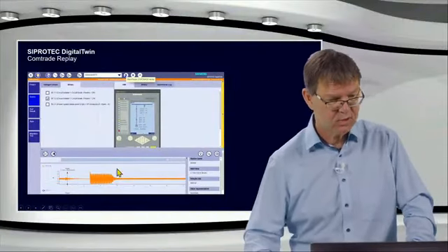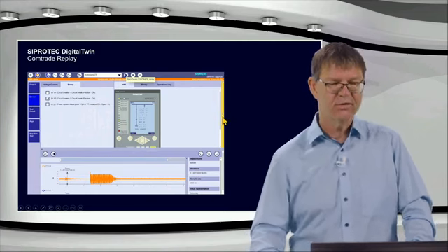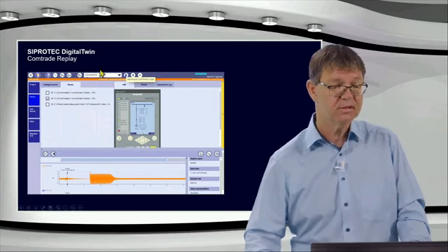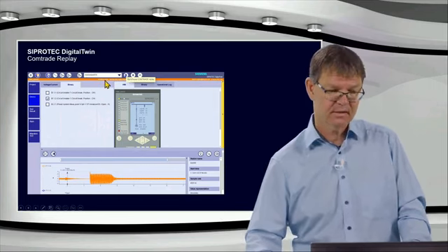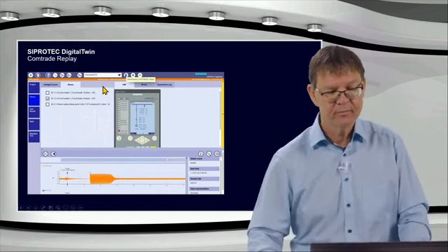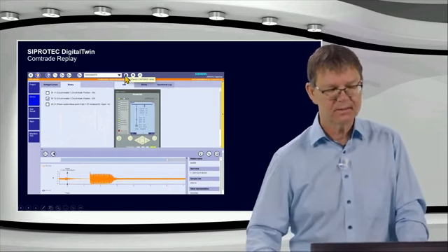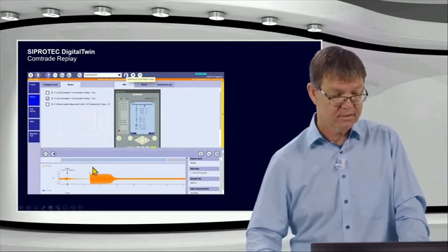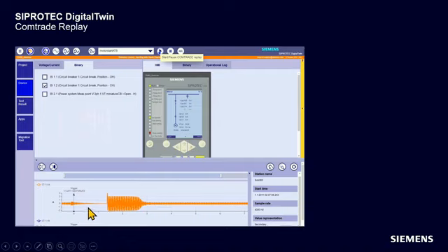Just one more thing which I would like to mention. You can also replay fault record. So if I have a fault record in a COMTRADE format like this here one, then I click here, I select this before and make some configuration. Then I click here on this button, start button, and then I replay this fault record. Here I can visualize the fault records, the traces here, and then I can replay this onto the relay, and then the relay and see what is the relay behavior. So also one of my tasks, if I get fault records, then I replay them and see what is the behavior of the relay.